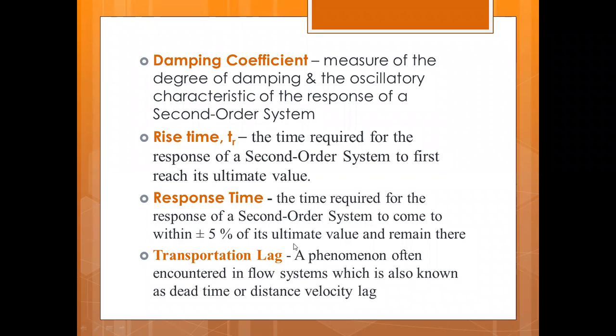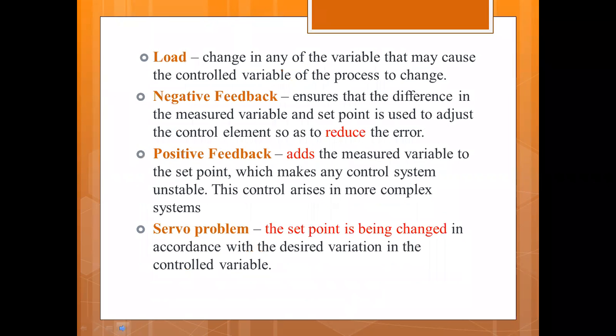Now, transportation lag, a phenomenon often encountered in flow systems, is also known as the dead time or the distance velocity lag. The load is the change in any variable that may cause the control variable of the process to change. The change in any variable, not just in the input to your system, that may cause your control variable to change is the load.